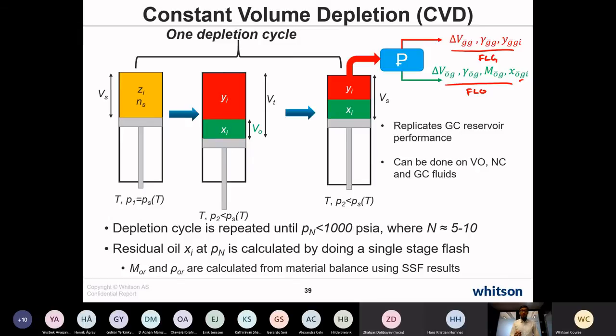For example, Core Lab generally uses the cryogenic flash. In the cryogenic flash, they use liquid nitrogen to freeze this equilibrium gas so that they can extract the maximum amount of liquid dissolved in this equilibrium composition, and then do the mathematical recombination more accurately.